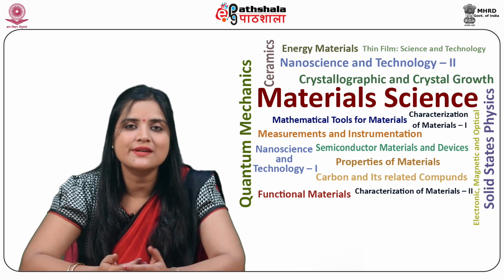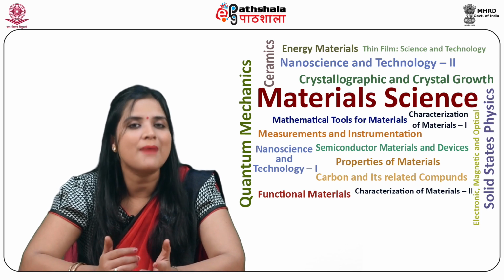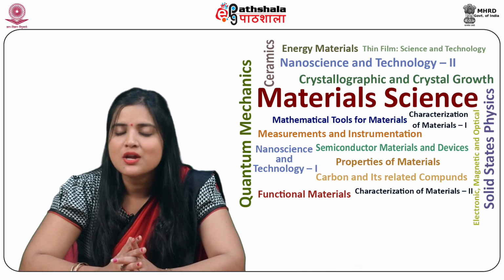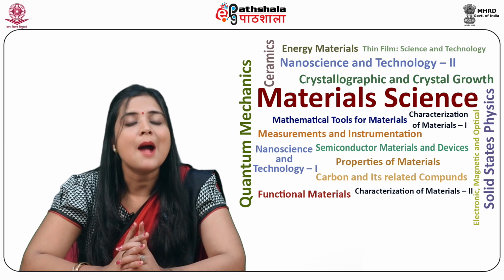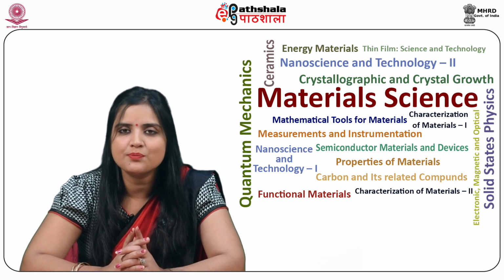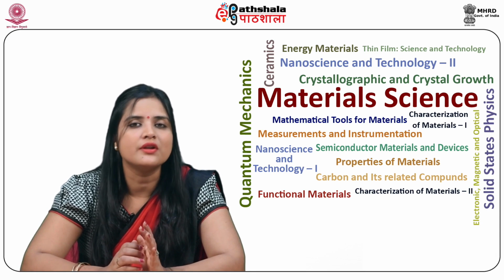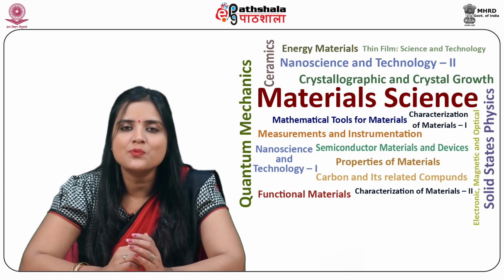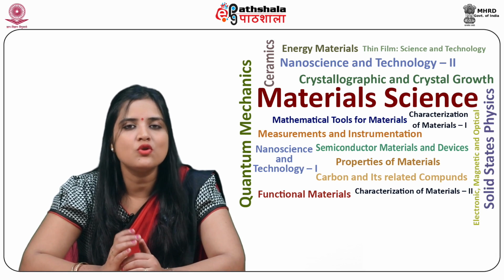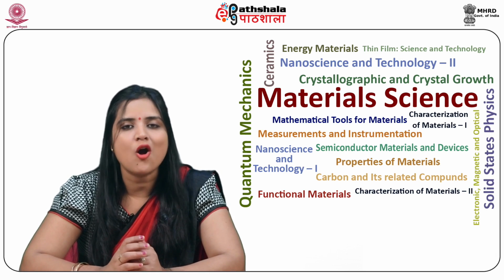Let us now discuss the next application of operational amplifier, which is the comparator. A comparator, as the name implies, compares the input signal applied at one of its inputs to that applied on the other input, which is called the reference signal. In this application, op-amp works in the open loop configuration, having two inputs and one output.